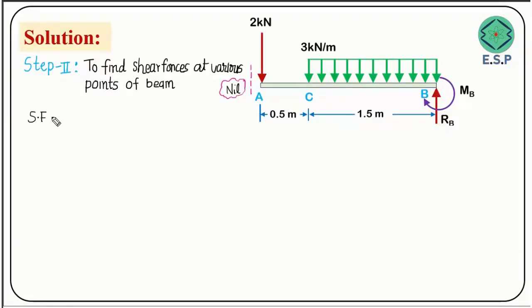So I'm going to write the shear force just before point A, which I'll call just left. J stands for just and L stands for left. Just left of point A, and then there will be the next calculation just right of point A. Like that we will be moving our plane from just left to just right. When I am just left of point A, no force has been covered by this plane, so it is going to be 0.